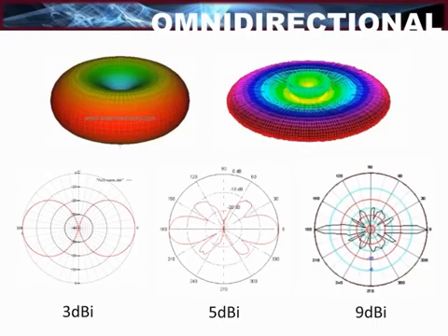The three-dimensional torus shape of this graph is illustrated at the top left. The bottom center graph illustrates a dual element antenna. This is the same pattern that was just described by two waves combining with each other. The three-dimensional version of this graph is illustrated at the top right. The bottom right graph represents several antenna elements. It can be seen that the more elements that are added, the more elongated the primary lobe gets. This is effectively increasing the gain or the focus of the antenna.